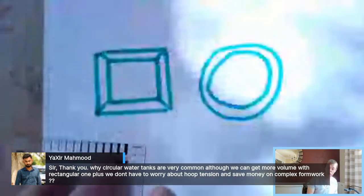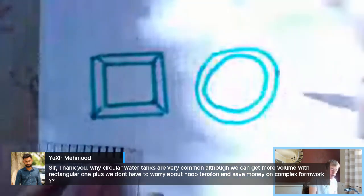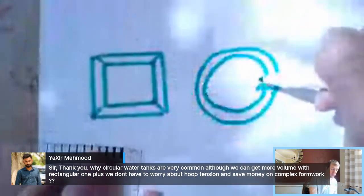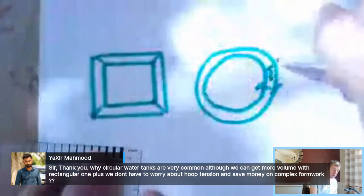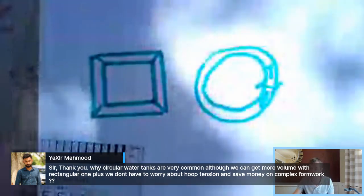Reentrant corners cause cracks. This is much more efficient. You need a much thinner member here, because the stress can be held much more efficiently by the hoops that go around the outside. So you'll see everything from grain elevators be circular as opposed to rectangular. So let's go back here.